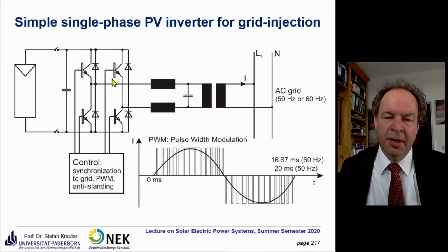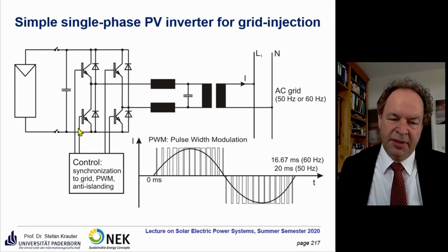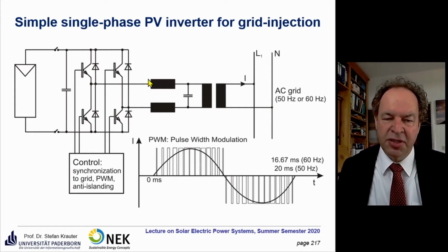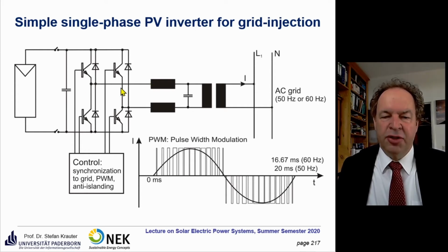Yeah, a very simple inverter, the 4-pulse inverter, a 4-switch inverter. So you have here 4 switches, for example thyristors or triacs or GTOs or IGBTs or even MOSFETs, and they are controlled here by the gate. And this control is made in such a way that you have either that or that in conducting operation, otherwise you would create a short circuit. You put this here, and then you would have positive voltage on that part of the circuit. So you put this on a negative part, you ignite this and that, and you can create pulses by that.